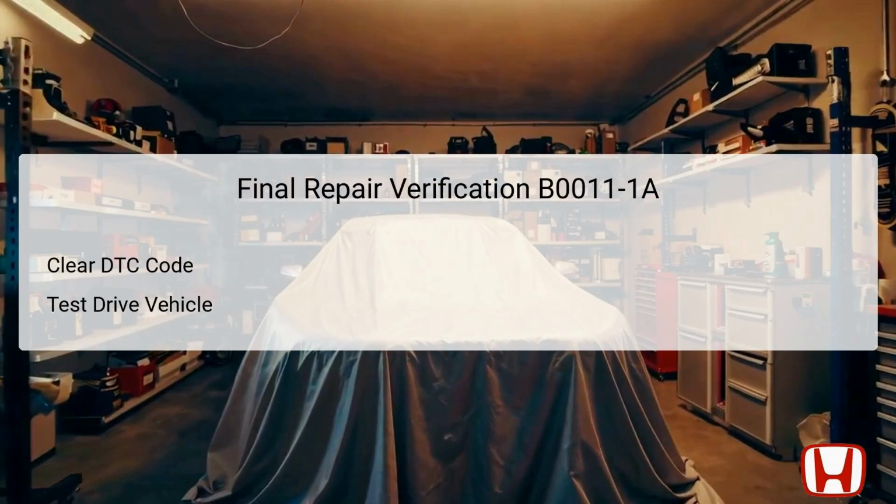After completing the troubleshooting and necessary repairs of DTC B0011-1A, it is important to clear the DTC code from the SRS system. This can be performed using an OBD-II scanner or diagnostic tool designed for Honda vehicles. Following this, conduct a test drive under various conditions to verify that the SRS system functions properly and that the airbag warning light does not reappear.